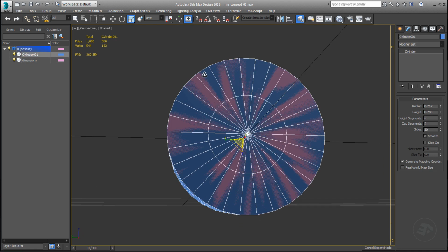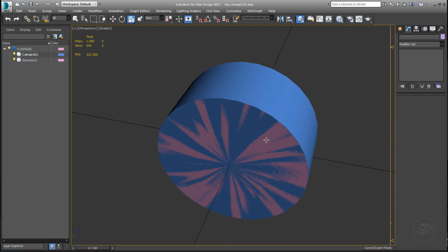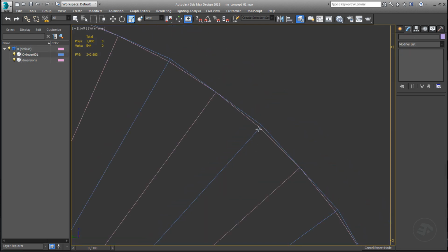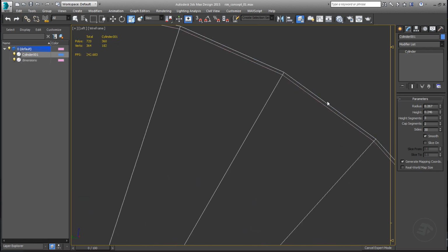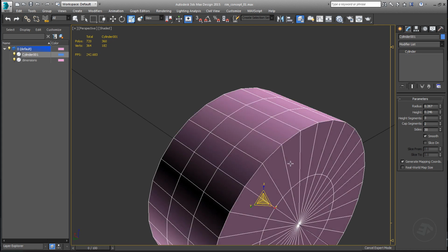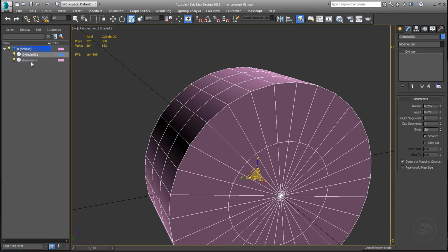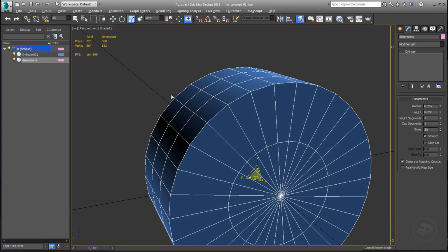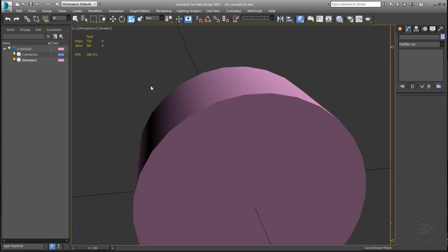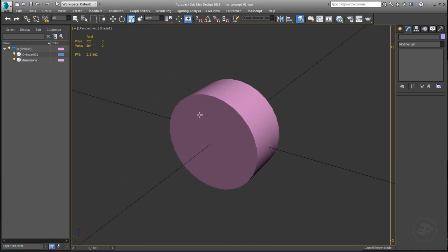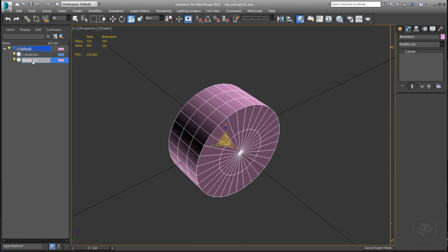The Turbosmooth will smooth the 3D object. During this process, the 3D object is tessellated. In order to smooth the geometry, a relax effect will be always associated with shrinking the 3D object at the XY axis. Unless Autodesk decide otherwise, the final result will not compensate any loss of the 3D object's dimensions.